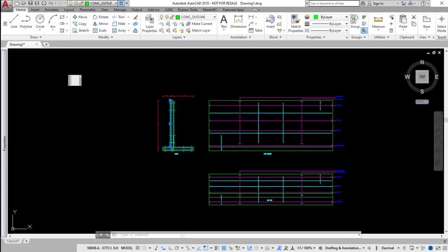If you load two walls into the one drawing, is the schedule revised to include the two walls? No. You would be doing two separate schedules for two different walls, and to be perfectly honest, you might want to do that so you don't end up getting the two sets of rebar mixed up. But no, it's a one-off at a time scenario on that.